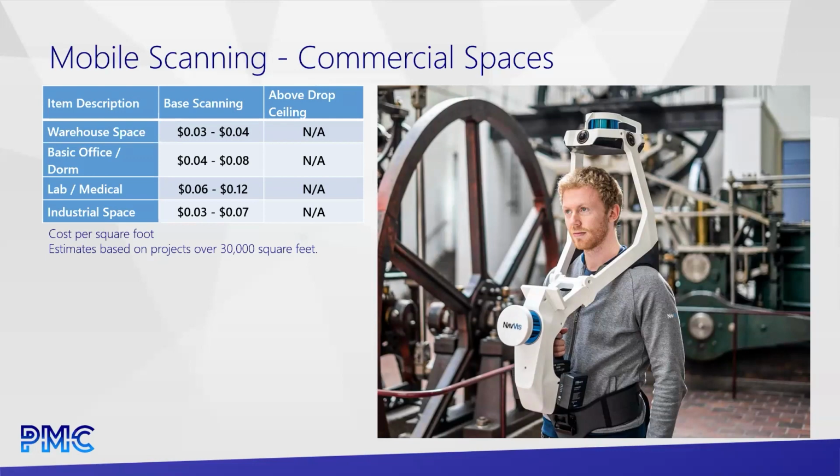But in the mobile scanning, we have to do survey at a smaller square footage size. Otherwise, this data starts to really fall apart. So there is a weird gray area in the middle where terrestrial can actually be cheaper than mobile. But for most jobs nowadays, mobile will be cheaper, and it works really well.